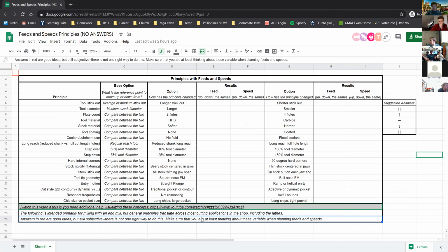So yeah, just a quick addendum about router world. There's a couple things that change. The biggest one is the fact that all of a sudden we're not working as much with blocks of stock as we are with plates. And if you've ever dealt with plate stock on the Haas machines either, plate stock is a whole different ball game. Nothing is ever fixtured well, just period.